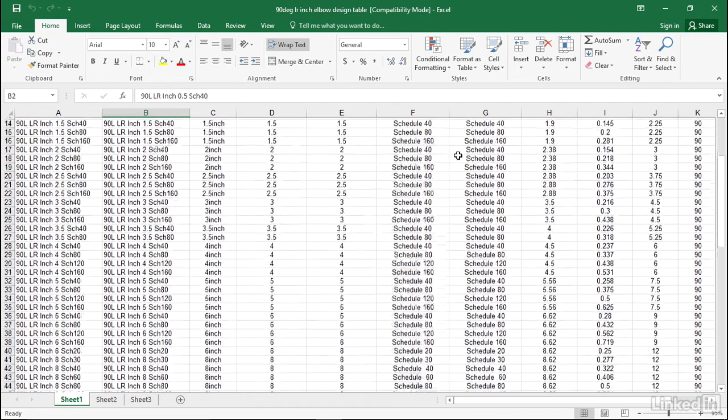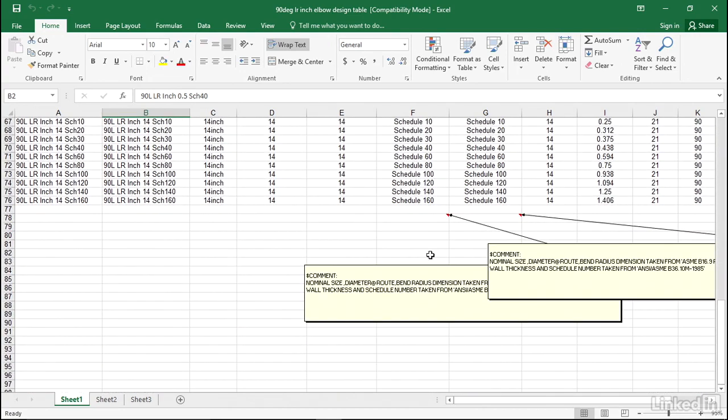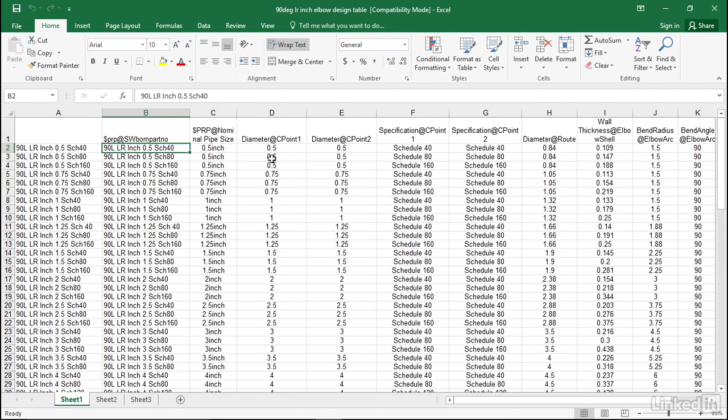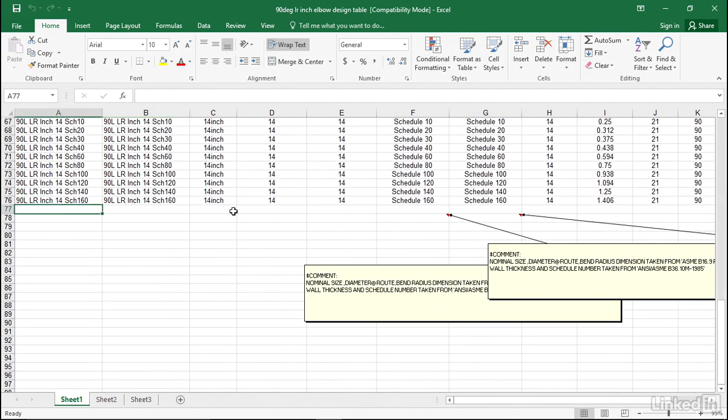If you want a little help or guidance on where these numbers actually came from, scroll all the way down to the bottom, and SolidWorks will have added in some comments onto the Excel file that you can see. Some of them are taken from various standards that are set, and some of them are set based on different lengths that they think you might need, for example, diameters or lengths. Now, if you wanted to add your own configurations, you can do that at the bottom with a different name, with all the dimensions laid out there as well.